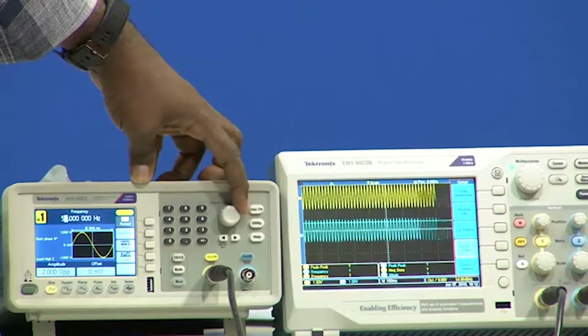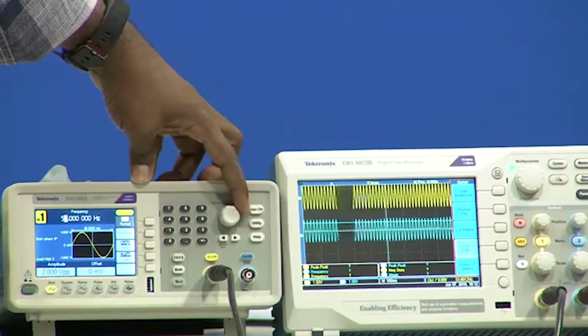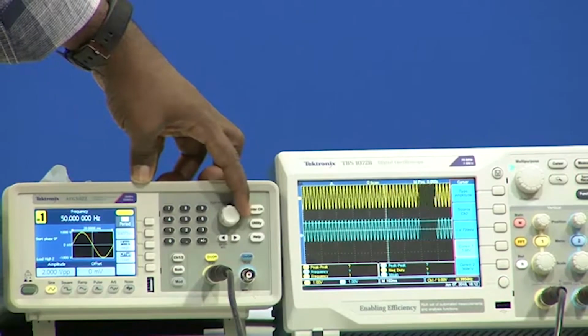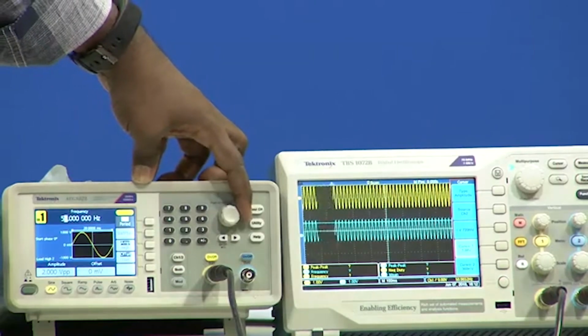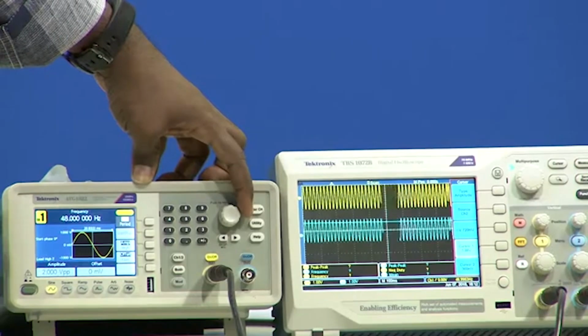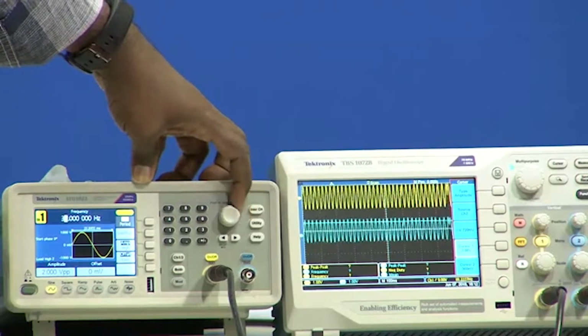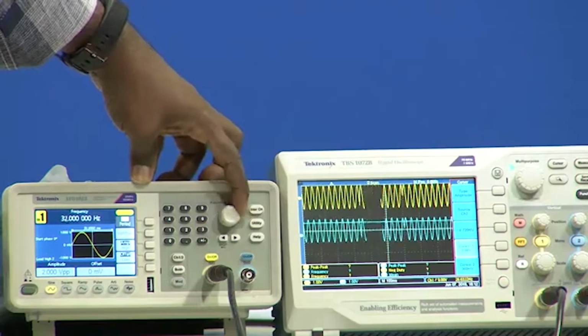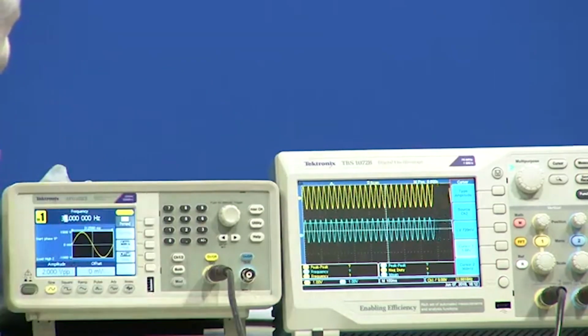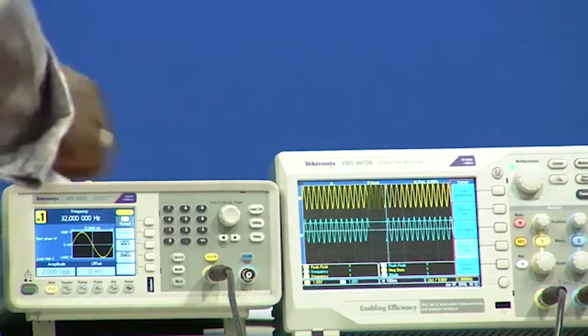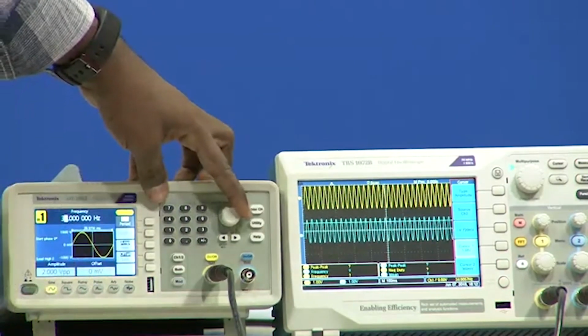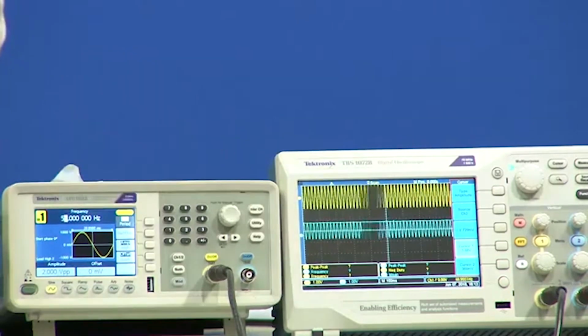I am decreasing somewhere to 53, 52 Hertz, 50 Hertz and 49, if it is higher. So, there was not much impact now. If you recall the pot resistance value that we have chosen, if I measure and select that same resistance value, we can see. So, I am adjusting the resistor. We can see it has come down.